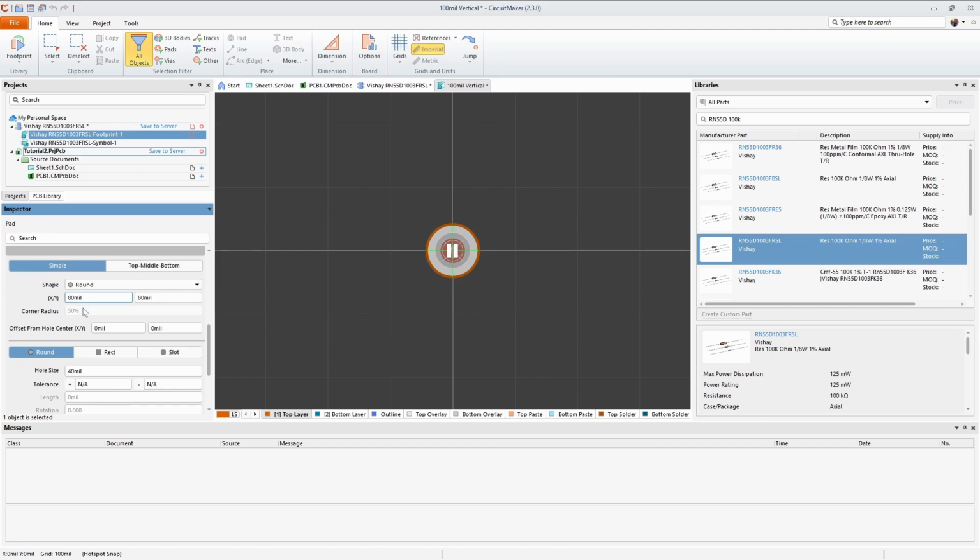But whenever it comes to making a pad to solder down to, you don't actually need the pads to be quite so big. If you do the math here, you'll find that the annular ring, the metal that goes around the edge of this hole, is already 20 mil wide, which is a pretty wide trace and a pretty good amount of area to solder to. On top of that, we're going to have solder filling in inside the hole, and solder can flow to the bottom of the board and on the pad on the bottom. So we have a huge amount of surface area to solder to here. I'm not that worried about contact.